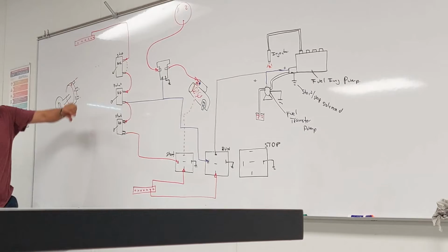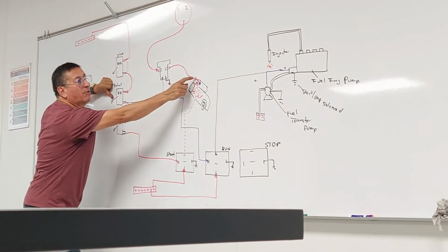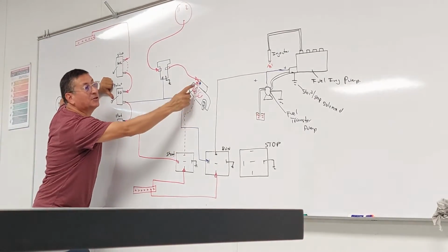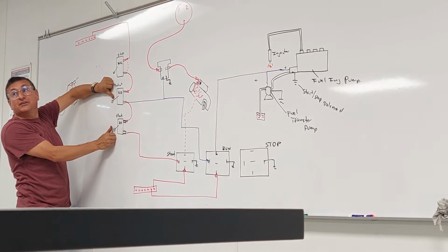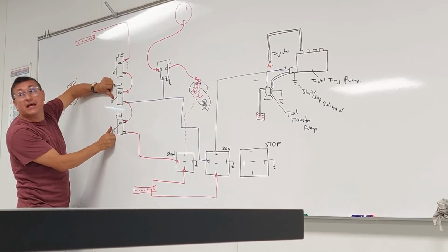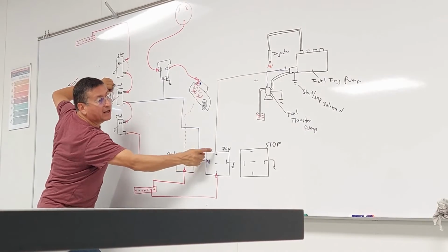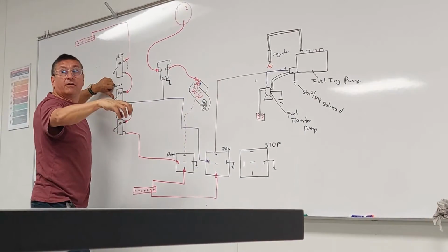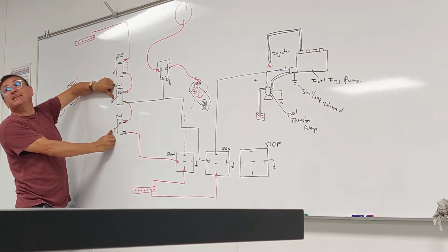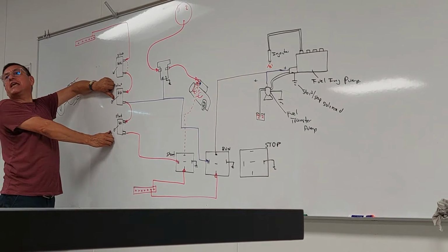Follow me. I press preheat. I bring power to the big one. I press start. I send signal to the start motor. Yes or not? Yes. The start motor is cranking? Yes. And the fuel is entering the engine? Yes, because look, I bring power here, the fuel transfer pump brings the fuel, and the solenoid opens, and the fuel enters. And because the engine is cranking, the motor starts. Wow, the motor is running.